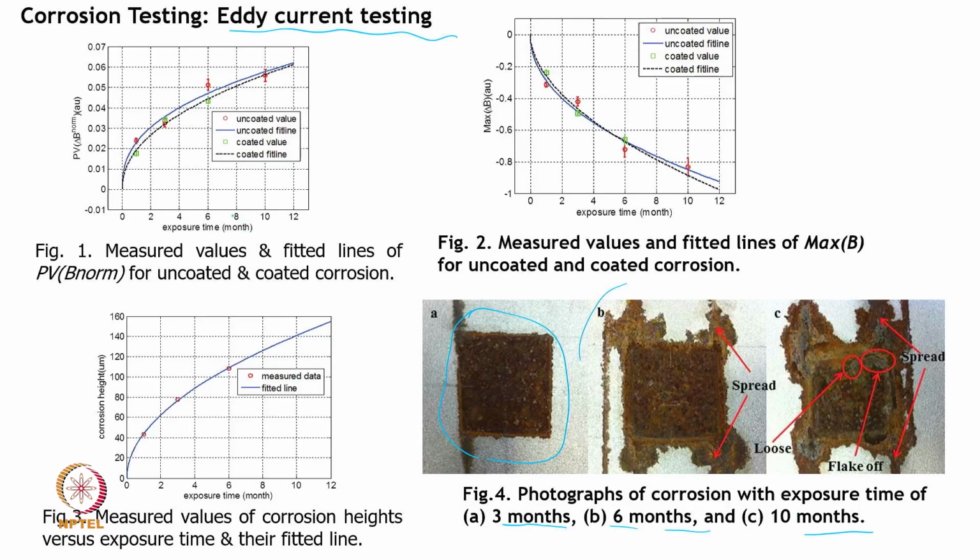You can see that they took 2 examples, coated and uncoated, and we know that in their results they found there is not a significant variation whether you are coating or not coating. So, this curve indicates how the passivation occurs in this situation and how the corrosion height is changing with time. With exposure time the corrosion height is continuously increasing, porosity will increase, and chances of failure will increase. This is what this slide has already covered.